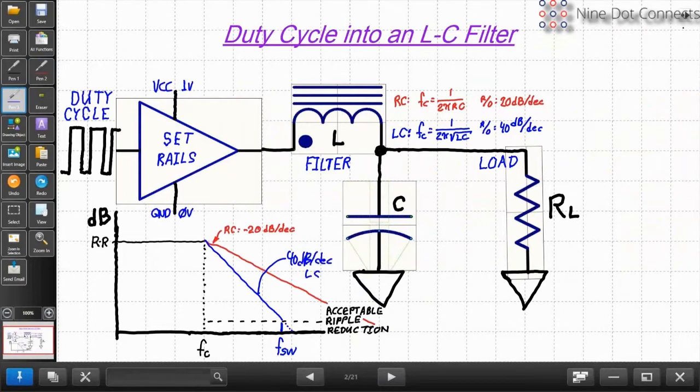That means that the switching frequency can be much closer to the cutoff frequency of the LC filter. That's really important when you don't have to have so many decades of frequency change. Inductors and capacitors have certain high-frequency limits, and you need to stay pretty far away from them to be able to keep efficiencies up. So that really, really helps.